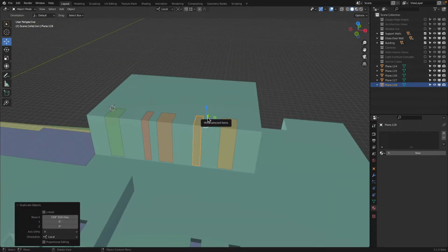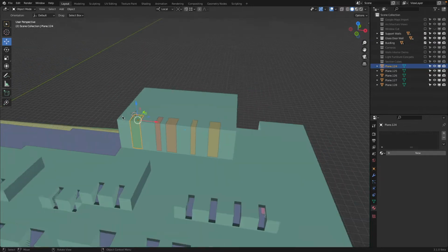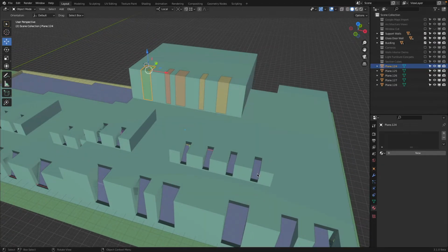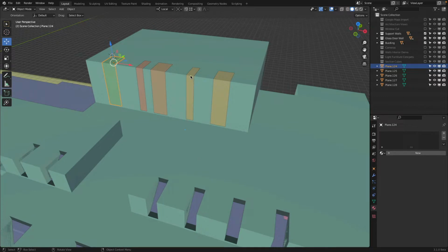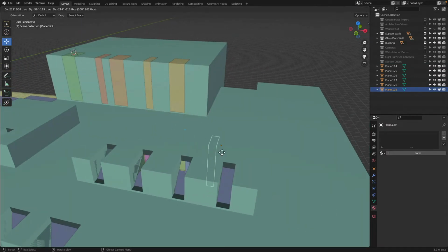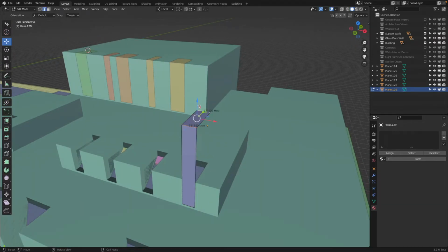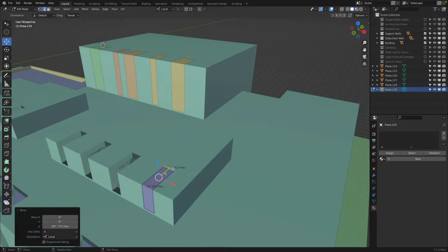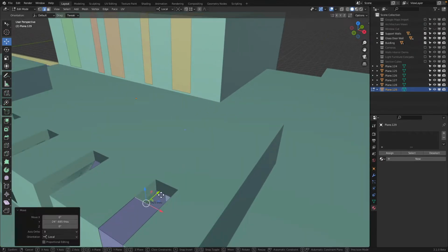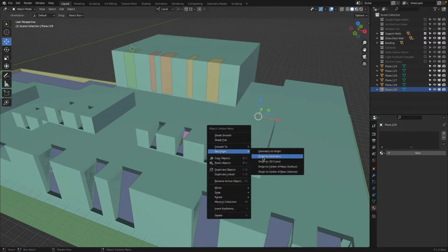Make a copy. Okay, we made copies on purpose because all these pieces will have individual materials. And it's a little bit different than here, for example. So I will do this. Shift D, hold Control, okay, to this bottom part, go into edit mode, move this down, hold Control, snap, bring this over, hold Control, snap. Okay, good. And then I will right click, set origin to geometry.